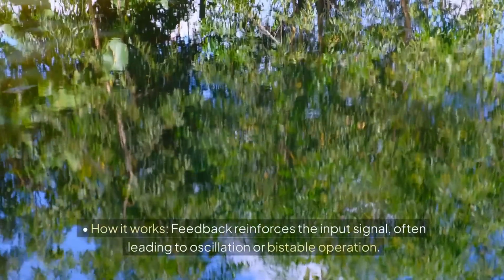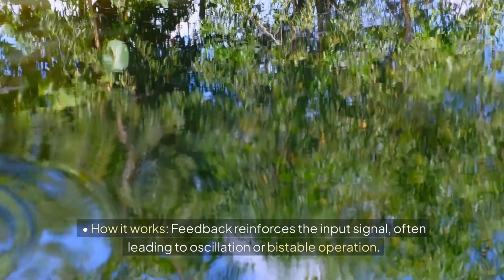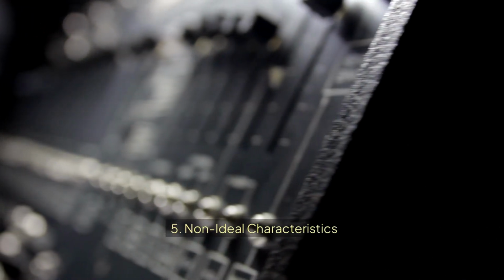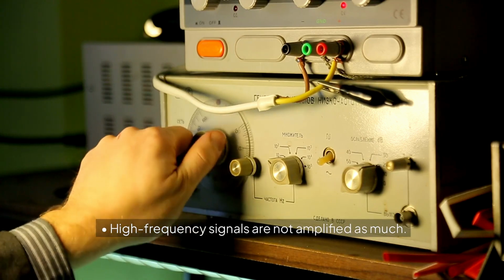2. Positive feedback. How it works: feedback reinforces the input signal, often leading to oscillation or bistable operation. Where it's used: oscillator circuits and comparators. 5. Non-ideal characteristics. Real op-amps deviate from ideal behavior in the following ways. 1. Finite gain and bandwidth: high-frequency signals are not amplified as much.